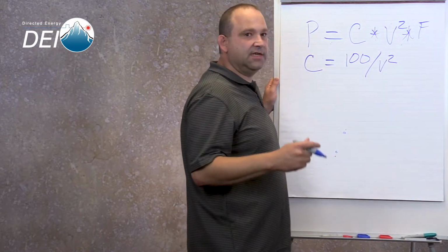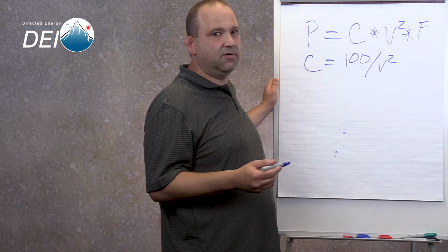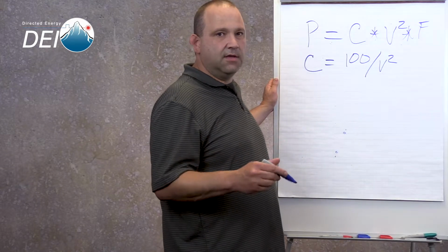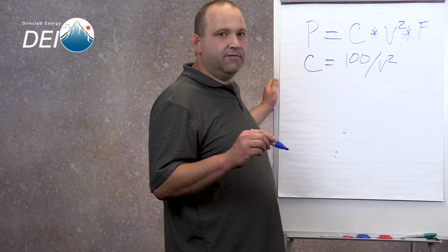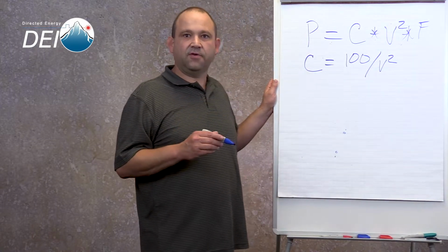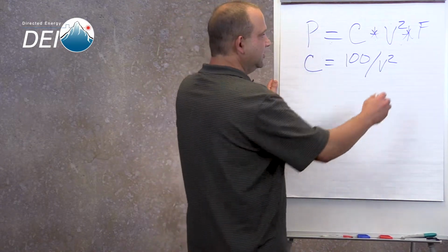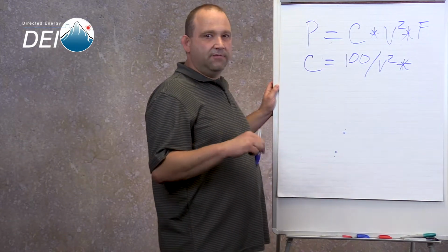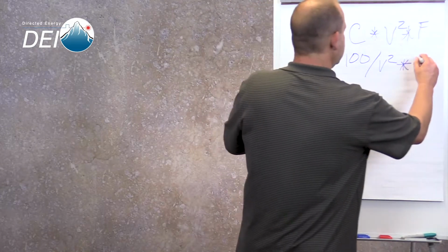Now the voltage is total voltage, whether you're going positive or negative on this, it is total voltage swing. So on a PVX-4100, say you're going positive 1.75 kilovolts and a negative 1.75 kilovolts. That's a total of 3,500 volts that you will need to use for your voltage, times frequency. Now you can pick any frequency you want. For this example, I'm picking 5,000 hertz or 5 kilohertz.